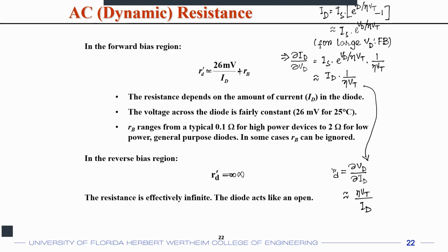So you already have bought a diode for this class for the labs, and if you measure the IV characteristic in the lab, you will see that it does not exactly match that exponential theory. This particular equation, in measurement, you may not exactly match it if you're considering VD over VT. So that's the reason why this eta factor, or the non-ideality factor, is considered.